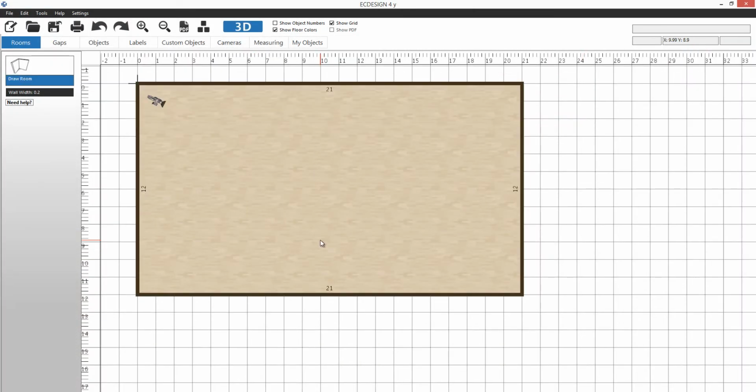The final sample I will show you is how you combine special floor options with special ceilings. And with that I mean if you have a tilted ceiling and you would like to have several different floor colors in a wide open area. Now normally if I had a flat ceiling I could just split the room in half and select another color here for this section and hide that wall that I create.